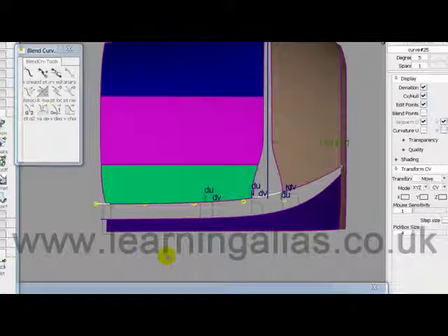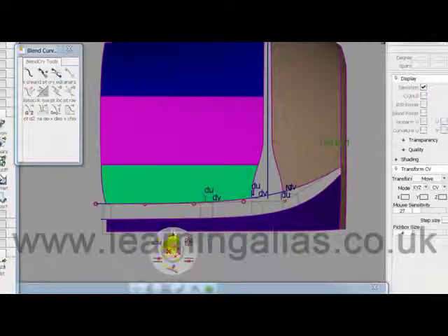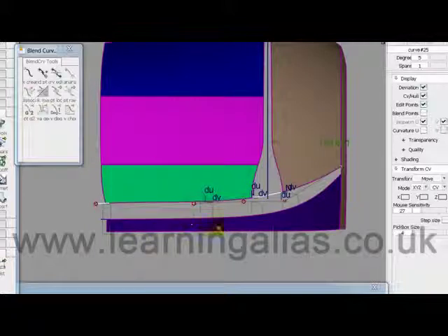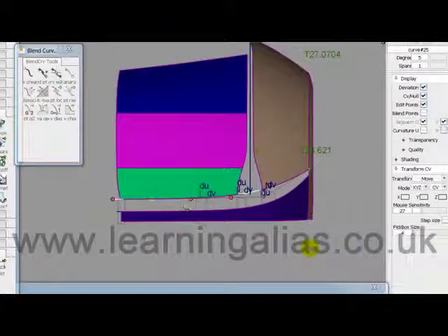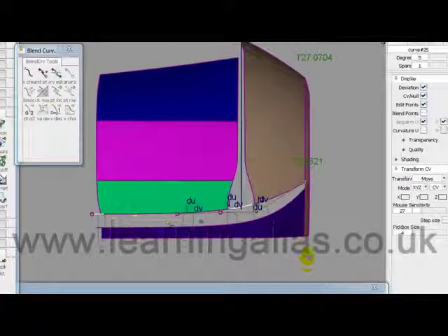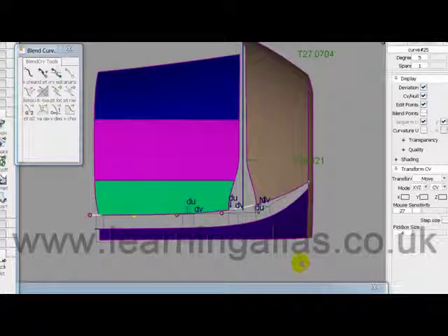And then one little thing I can show you, if I just pick this projection curve here, I'm going to shift Z, let's bring that up. I'm going to move that out of tangency like so, and then when you're setting up a curve like this, to get that point tangent to this point, just come here with your mouse, hover around there, push down Control and push the right mouse button, and you'll see that that snaps into tangency. So there's a little useful bit of information for you there. Okay, let's get on with it.